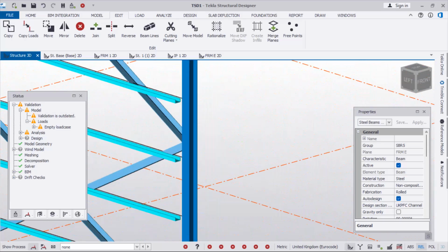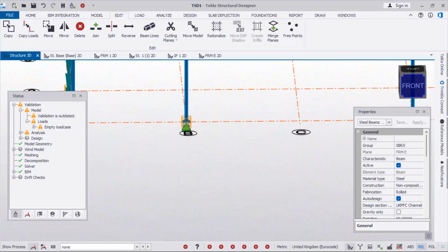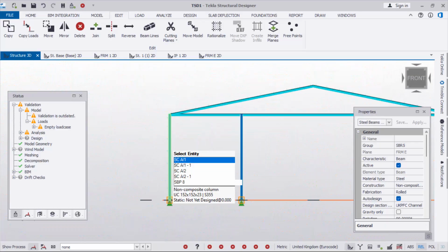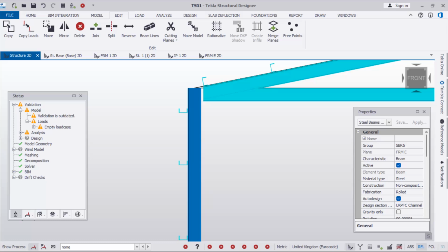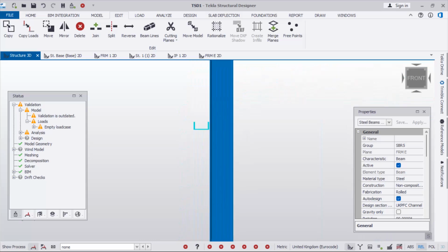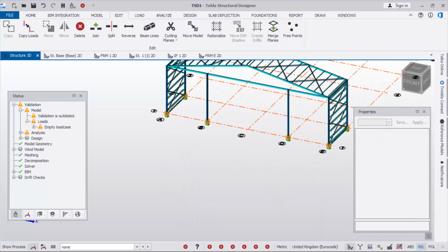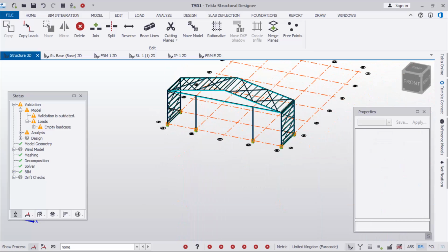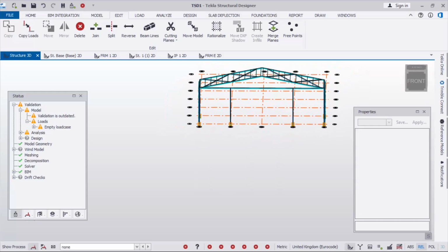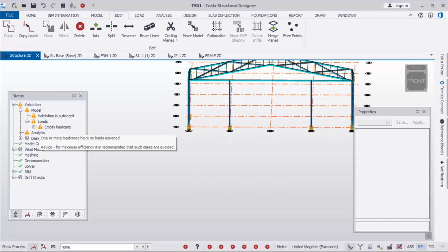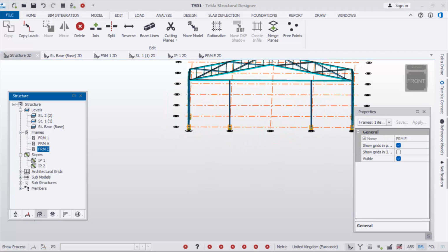And then after this, just come here to see if you have perfectly placed your bracings. And then you can just come and go to this and see how your purlins look like. They are perfectly placed like this. So what you're supposed to do now, just come here to level 1. I meant to this level, and just come here to structure, then you go to this frame,